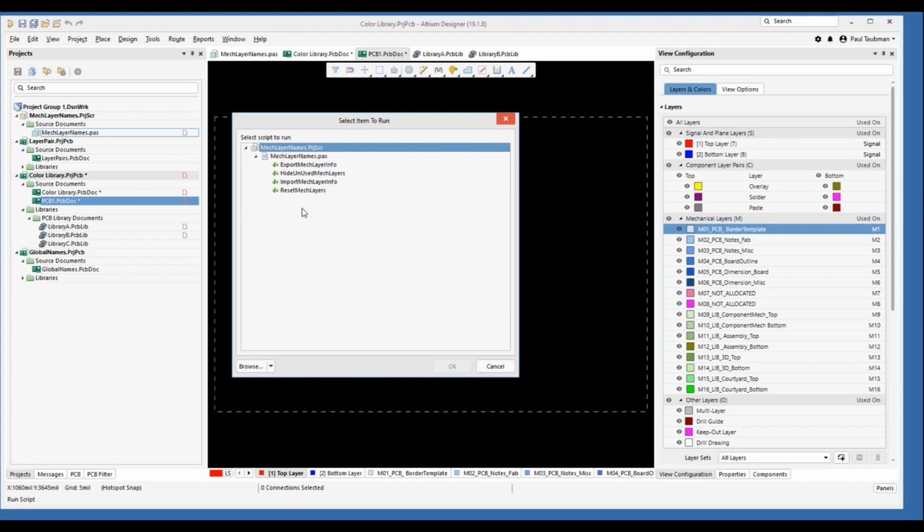The first one that I'm going to show you is the export. They also have an export and import feature similar to what Altium has, but there's a little caveat to this that I think you'll like, especially if you're setting these things up. In the Altium one, it didn't matter what you have over here, if you import something, it will blow it all away and import what you gave it. This one's a little more forgiving, and I'll demonstrate that in a moment.